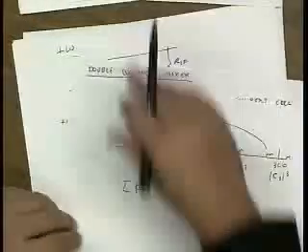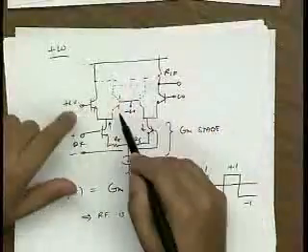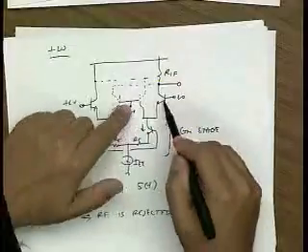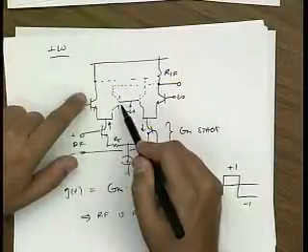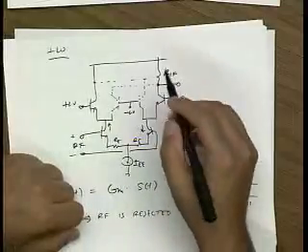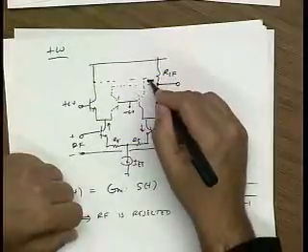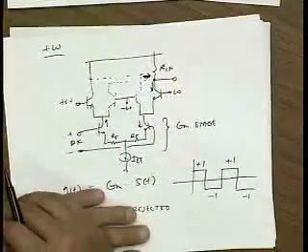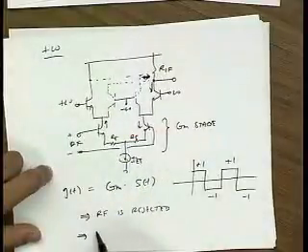In a double balanced mixer, the LO has two paths. It has this path to the output and this path to the output. And these two paths are wired up in an opposite direction. So the gain from this path to the output is, let's say, GM1. The gain from this path to the output is minus GM1. So the LO perturbation, if these two paths are perfectly balanced, the current from here perfectly balances the current from here. So this current balances this current, and none of the LO current actually flows into the output. So this voltage will not move due to the LO voltage. So the LO is also rejected.